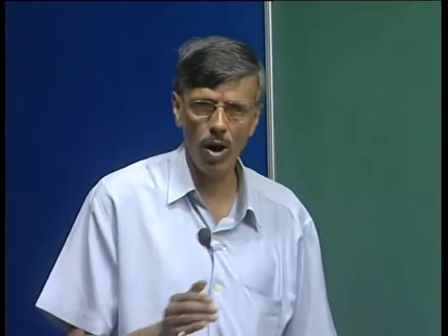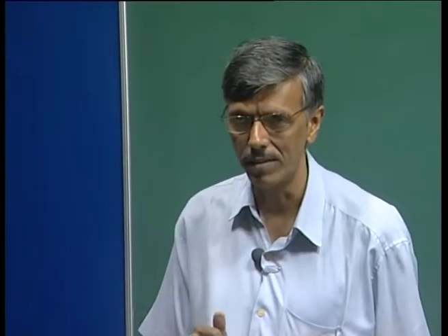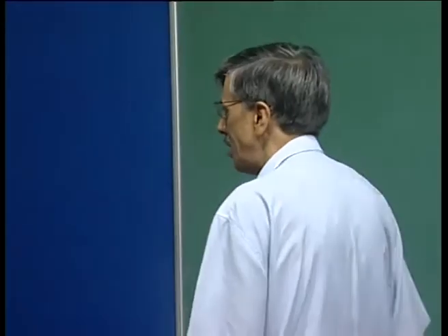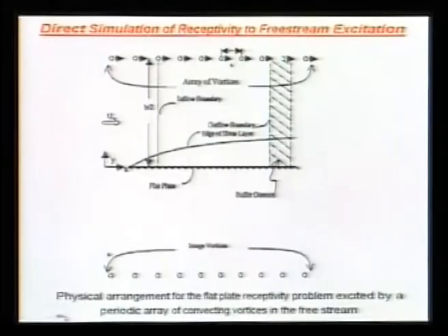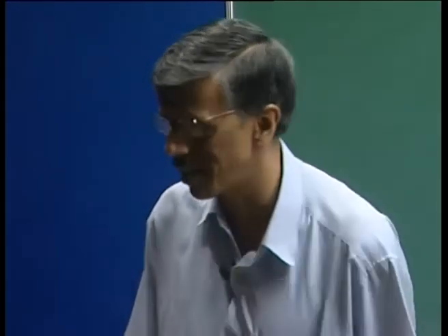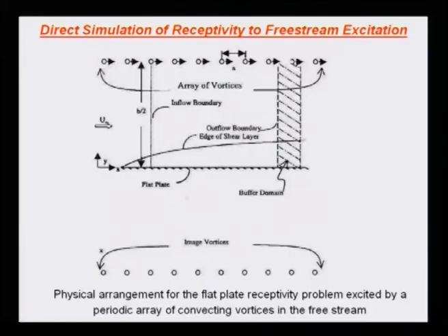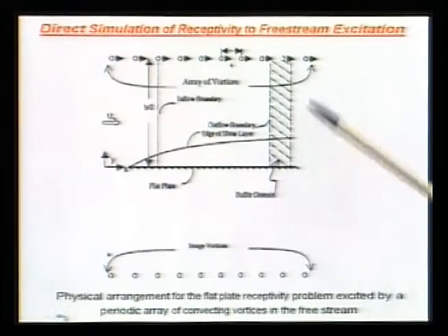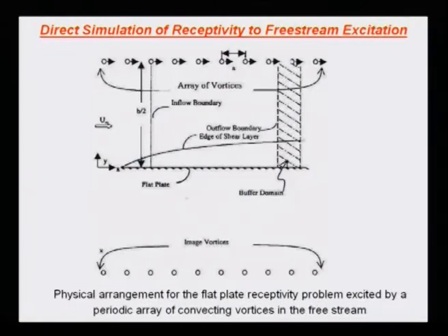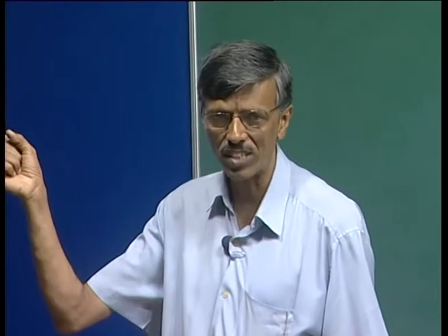If it cannot go out cleanly, then there will be some kind of a reflection, and that reflection can build up and lead to numerical instability. So to discern physical instability from numerical instability, we have to be very, very cautious in avoiding such spurious reflections. Okay? So what we could do is forcibly eject it out.